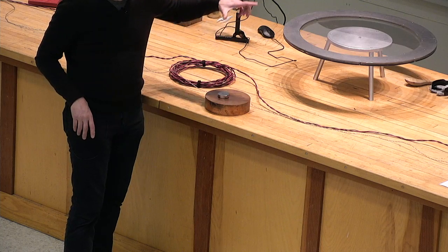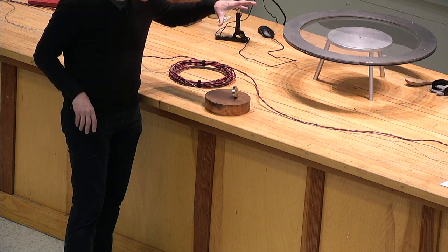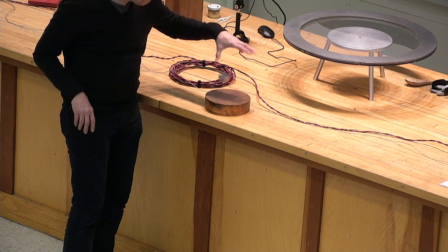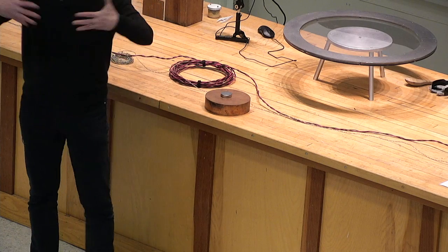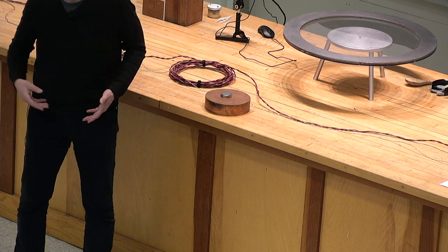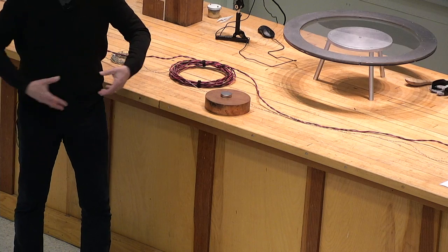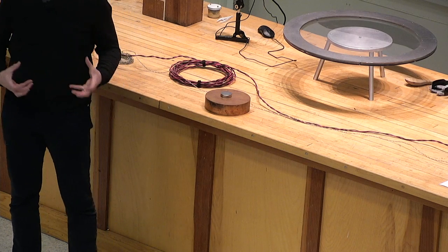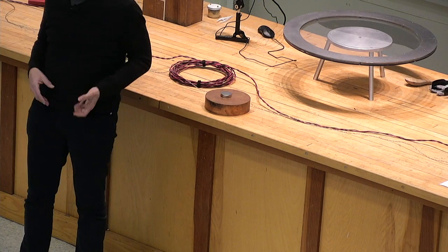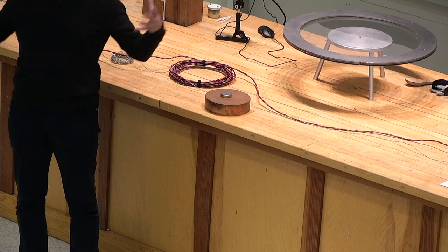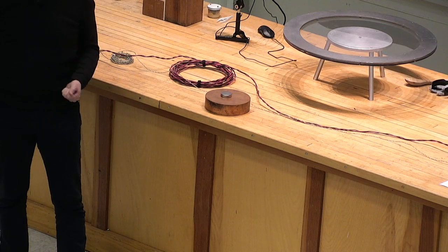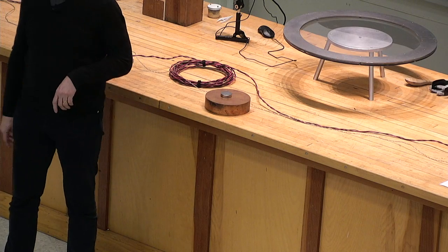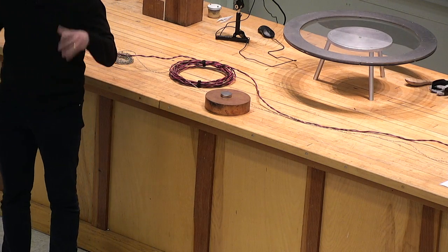They're not smacking into each other at all. The problem is, as that magnet approaches the copper, it's a moving magnetic pole, or changing magnetic field, whatever you like. An electric field shows up, currents begin to flow in the copper, and because that copper is a solid chunk of really good copper, the currents that flow are huge, probably thousands of amperes, a vast current. And that vast current by itself has a lot of magnetism.